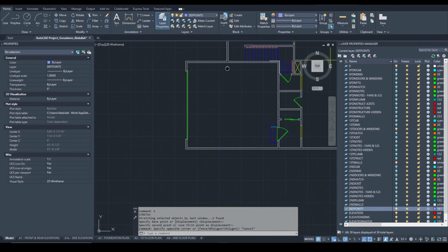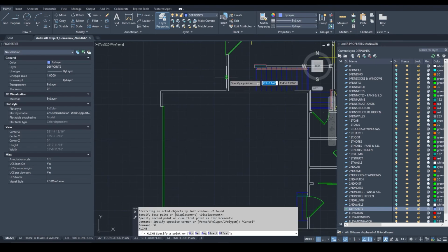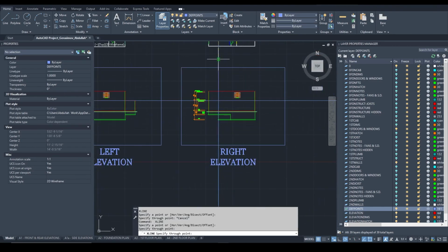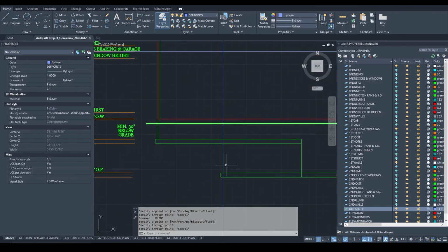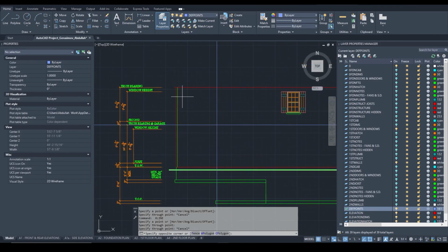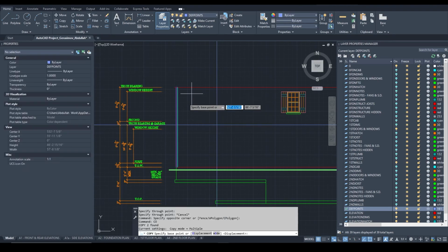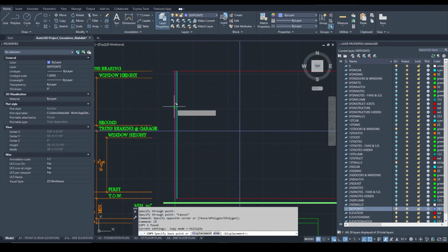But here you can see a portion of our elevation is visible on the left side, as well as the portion of our second floor elevation is visible. So what we're doing, we're going to the depth points layer, drawing another XL line from the area where our second floor is starting. As you can see, it aligns with our foundation line below.